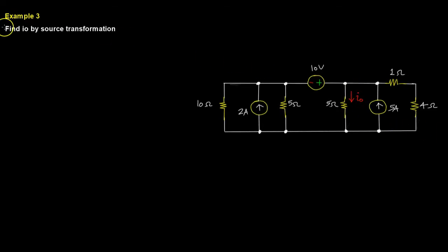So I'd like to find the current through this branch, and so I'm just going to leave that branch alone. And I am going to note that the assumption here is this particular polarity because of that current flow. I'm just going to leave that branch alone and work on everything else. So let's think here. I see a current source. I'm going to think about where its current would potentially be going. The current could be going this way, this way, this way, and elsewhere, of course.